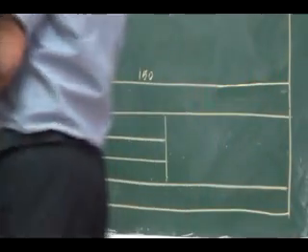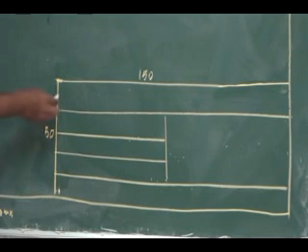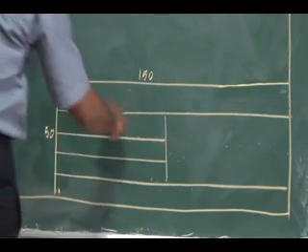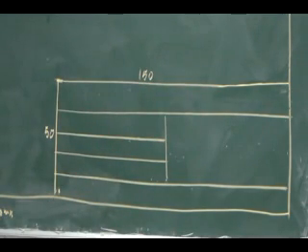Now inside this, for the first height of 10 mm, I can have a 5 mm height to write the details of the drawing, the name of the drawing, whichever topic you are drawing in your units, or whichever topic you are drawing in the drawing sheet.